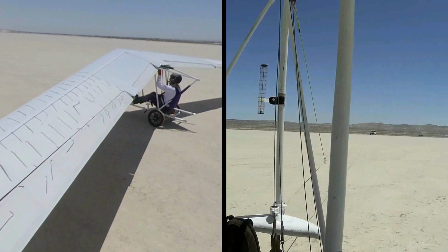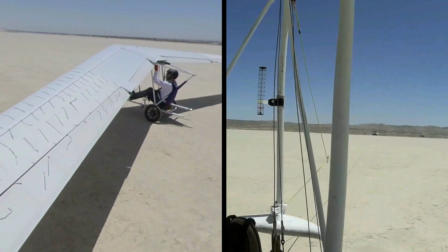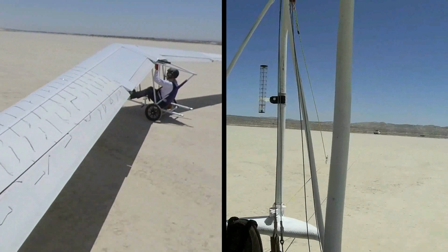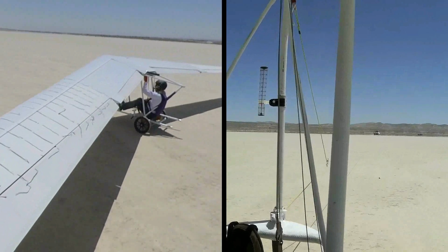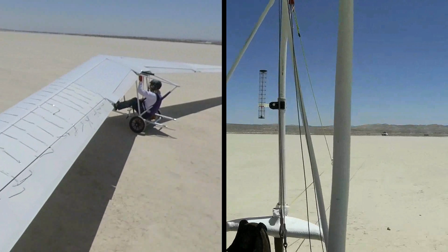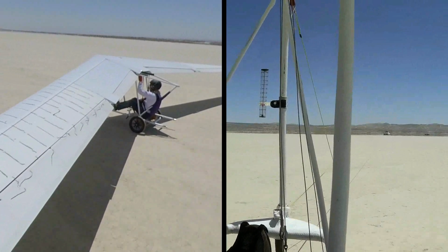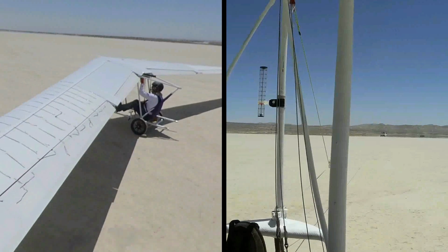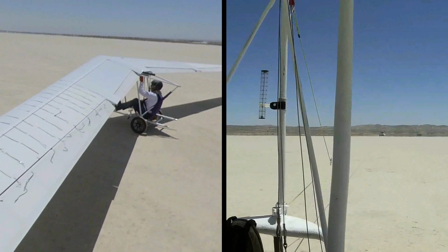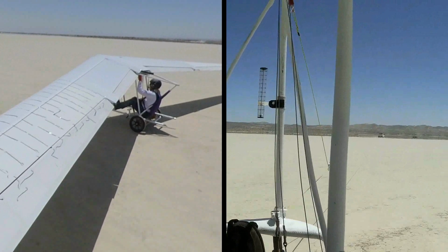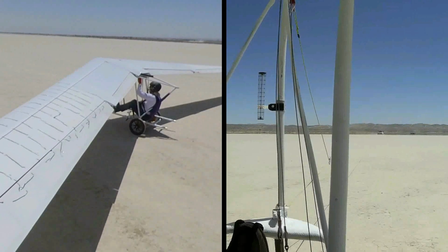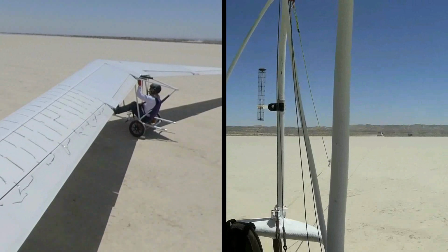And we're rolling along here. We start to see the airspeeds coming active. We're up to 10 miles an hour. And as we hit about 10, the flow improves on the main wing, but it's still going out span-wise along the elevon. If you follow the link in the video description, it explains how that flow can go straight back on the wing and then turn 90 degrees and go out to the wingtip. It's the most bizarre thing in the world. But it's all due to Reynolds number and the velocity of the aircraft.